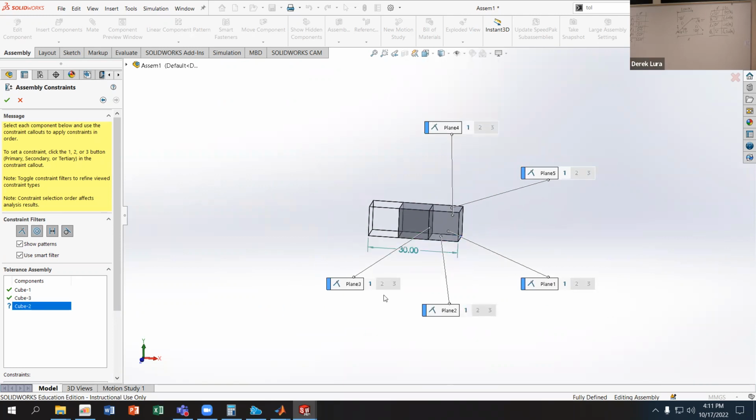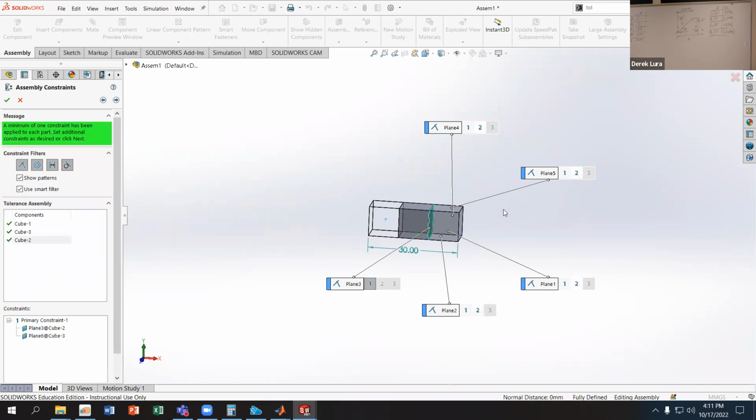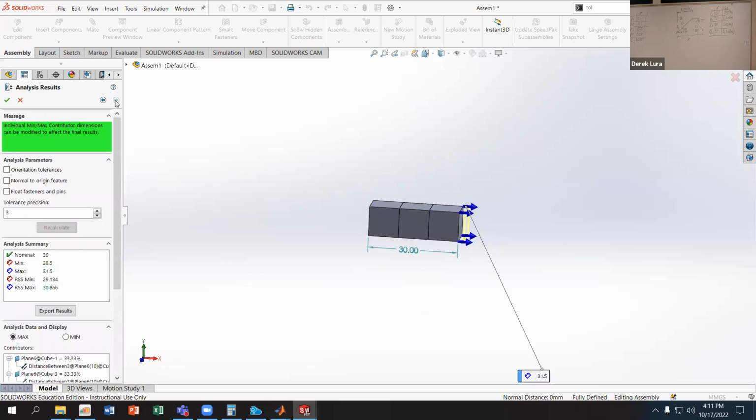And the same thing, I'm just going to do the touching faces as the first alignment. The bottom faces as the second alignment, because it doesn't really need the rest of them on this one. I want to put them there anyways, because it already turned green on me. And then the side faces as the third alignment. And we're green, we can go on to the next one. I think on this one, it probably only needs the primary because things are so simple. Then it says, hey, here are our results from the simulation,